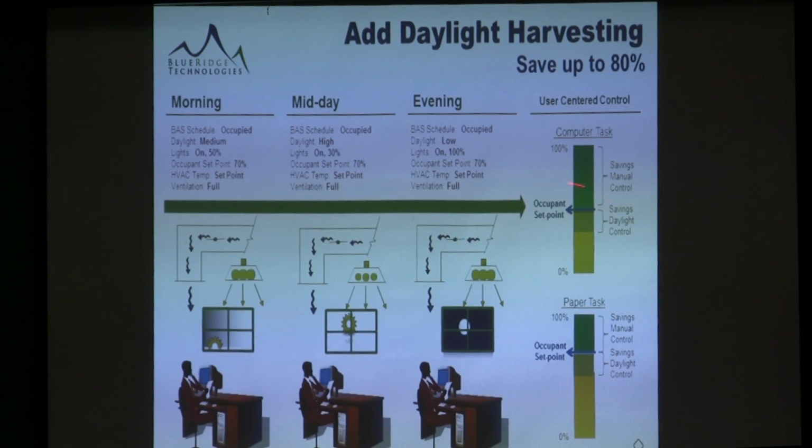The other thing that we've done on our controller is we've given you two control strategies. One is the traditional daylight harvesting, where there's a set point that you would adjust basically through the BACnet side of the world. You go in and calibrate that, and it's a fairly intensive commissioning process. But we said, there's probably a better way to do this, which is let's let the occupant choose the set point, just like they might do in temperature control. We allow them to set their lights wherever they want, within the ranges that I talked about earlier, if it's a dimming fixture.